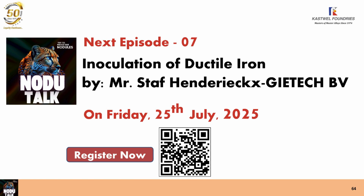You have a silicon range to get your final perlitic or ferritic ductile iron. The only exception is the 4% silicon molybdenum. The 4% silicon molybdenum has a very high silicon content, and there they have a lot of problems with dross. So it's very important that you restrict the magnesium content in this type of metal very much. Otherwise, you will always have dross.